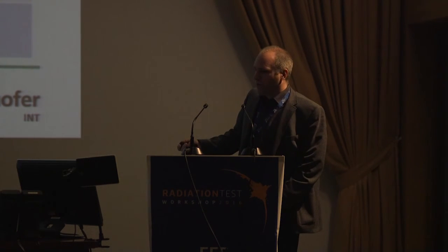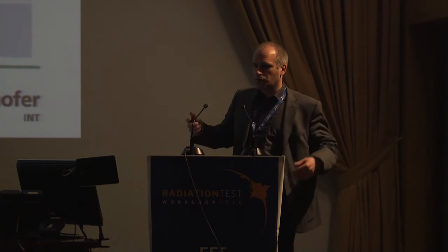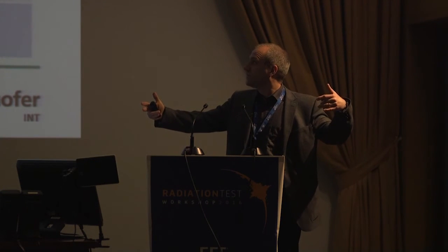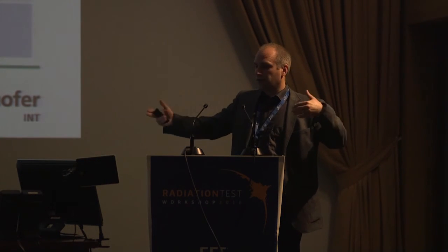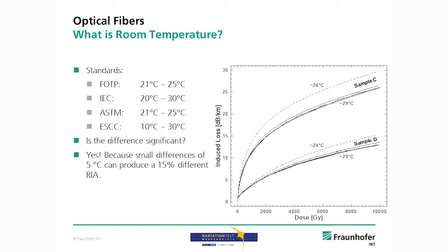And the length is very dependent on the sensitivity of your fiber, because you don't want to have too large a difference of the light power inside the fiber. So you have to tune your lengths. If you have a very radiation hard fiber, you might need 250 meters. If you have a very sensitive fiber, you're down to a few meters usually.